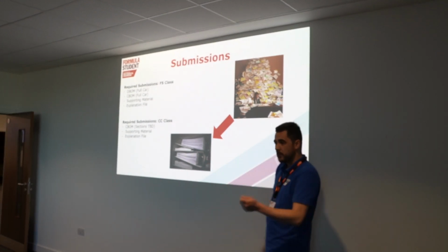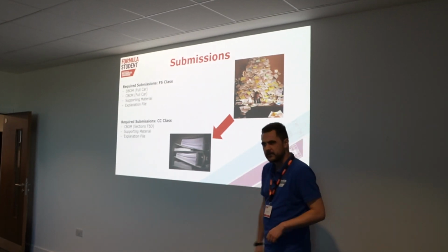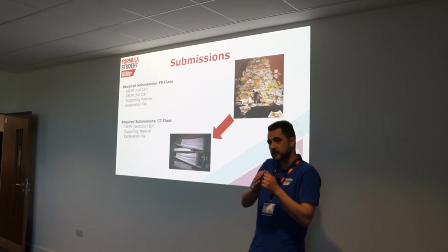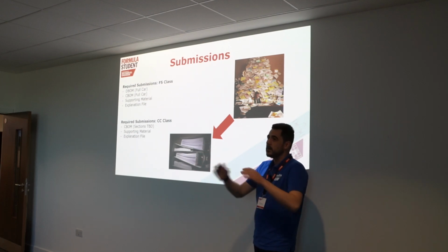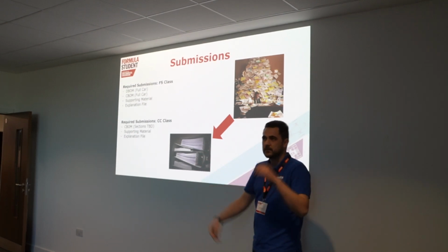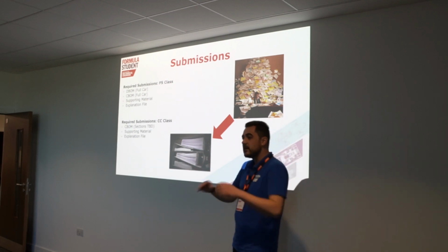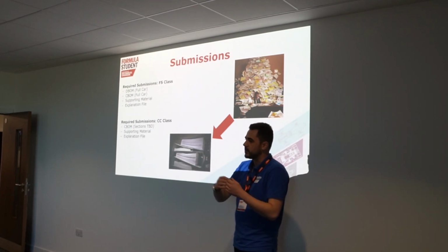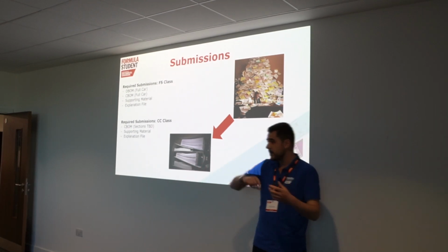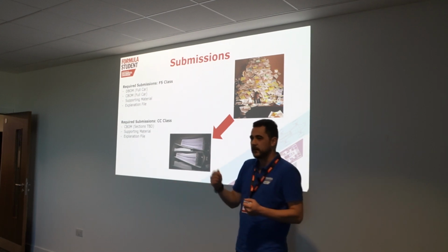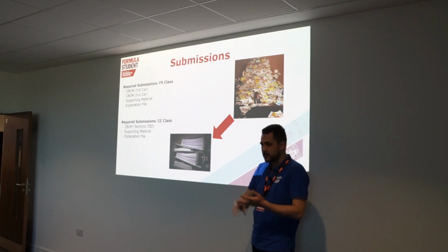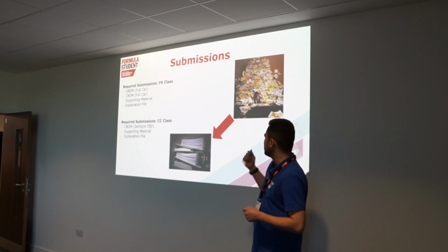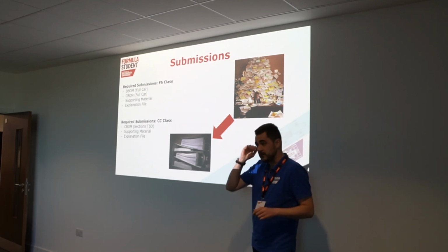If you've got a pen or a notebook in your hand, go, right, okay, how did they manufacture that? What were the processes that went into it? And just get bigger and bigger, and then eventually you'll be able to look at your car and go, right, wheel assembly, that's that, nuts and bolts on that, okay, we're going to need Loctite on that bit. And you'll picture it and you can see it. You know how you have an exploded view in CAD drawings or on technical drawings? You need to be able to do that in your head. Work out every part that's in it, every manufacturing process, every material. It makes writing the bill of materials easy because you can see it.